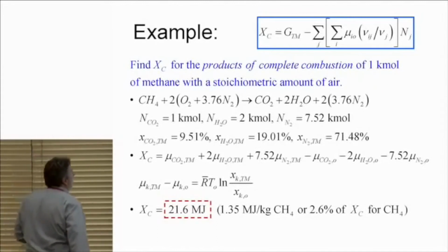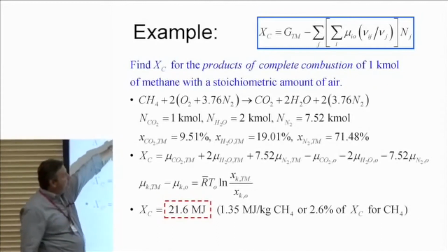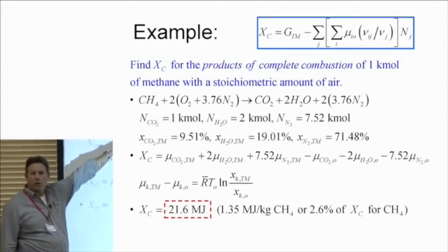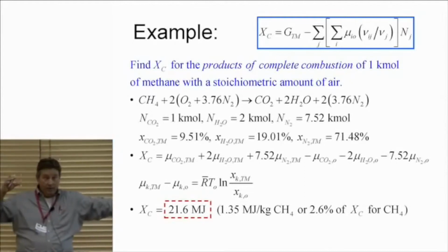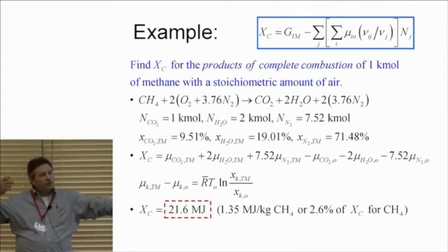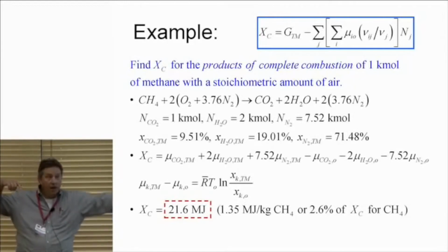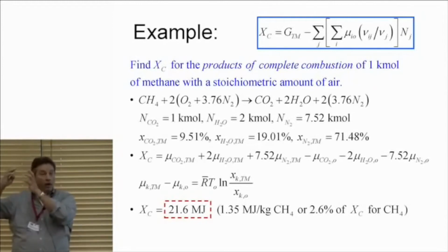What if I do the exergy for 1 kilomole of pure CO2? So I have CO2 and I let it diffuse into the atmosphere at 370 ppm. How much work can I get? This is reversible, right? So that's the same amount of work, the minimum work required to take a kilomole that's at 370 ppm and pull it to be pure at 1 bar at atmospheric pressure and temperature.